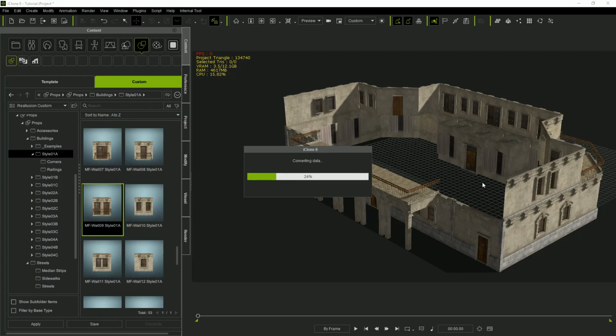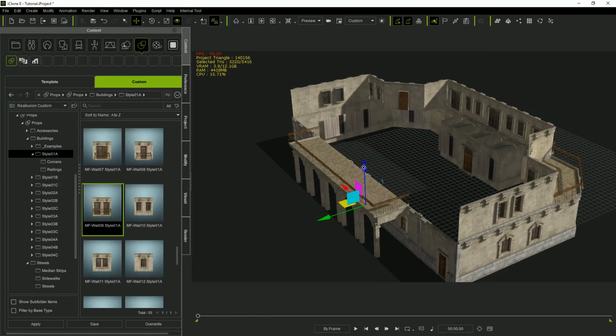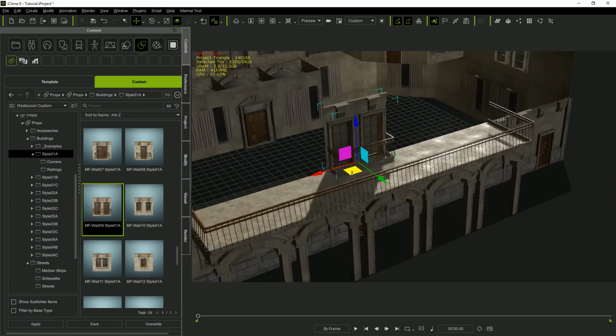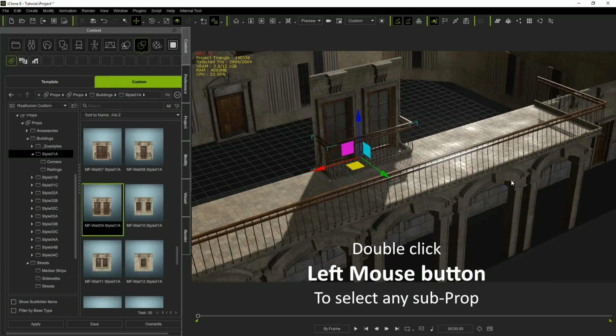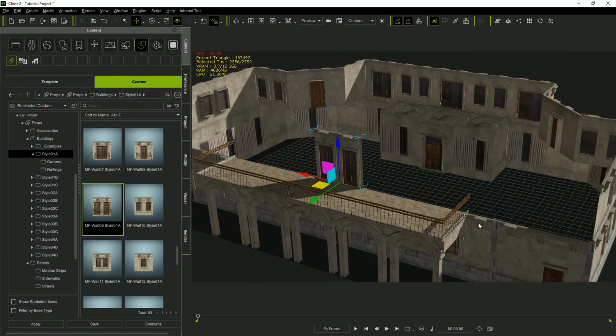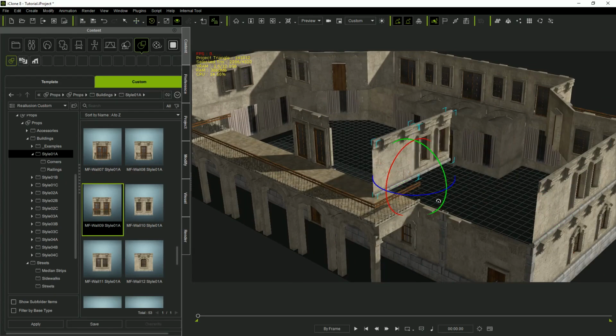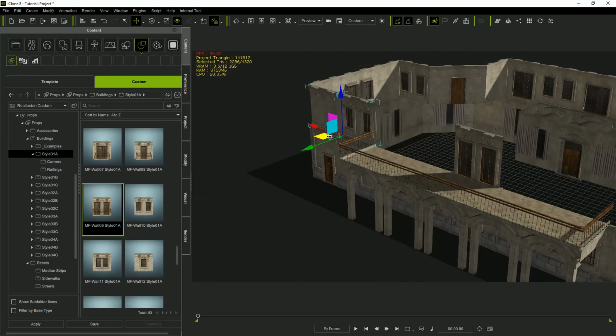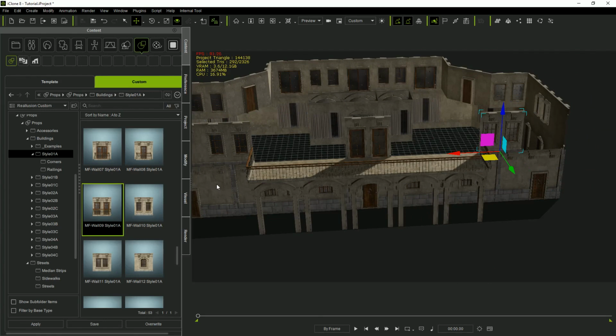In the back wall of the first floor, we can start with a balcony module with a single door, but as the balcony overruns the terrace that we made over the arch modules, we can select the balcony, double-clicking on it, and simply delete it. And so we keep adding modules from the Content Manager or duplicating modules from the building.